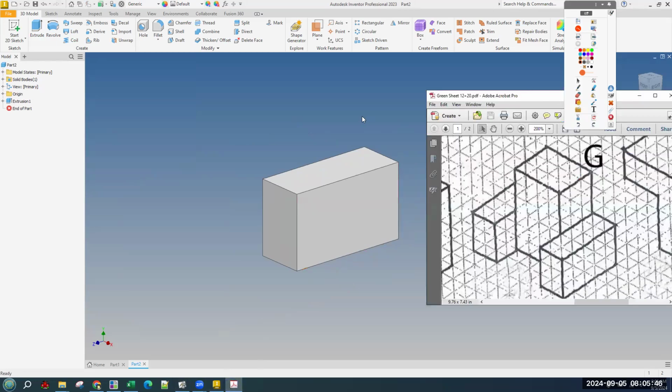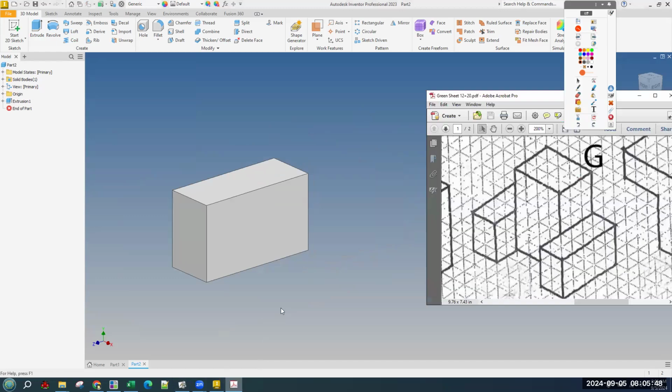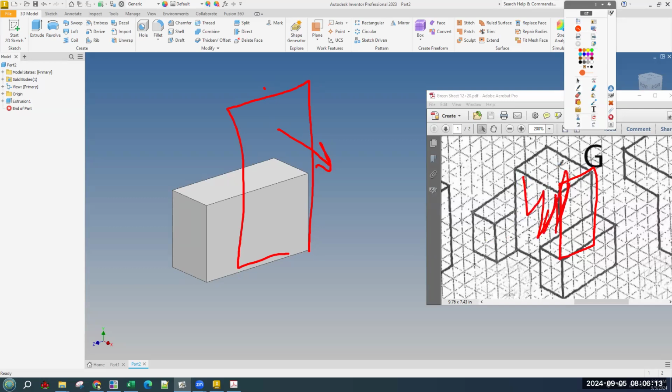Okay, so here we've got just the right side, or left, again, technically. It's just this part here. Now, to draw the top part, this is the face we have to sketch on. So I'm going to make a rectangle that is essentially this shape, because if I make it this shape, I can extrude it this way, and it will make the center vertical part.